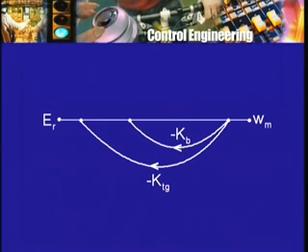So this loop is not something physical, it is something only conceptual, in terms of signals or equations or transfer functions eventually. The other loop is a physical loop, in the sense that the tachogenerator is mounted on the motor shaft and you connect the output or the armature of that tachogenerator to this difference device. There is an actual physical connection.